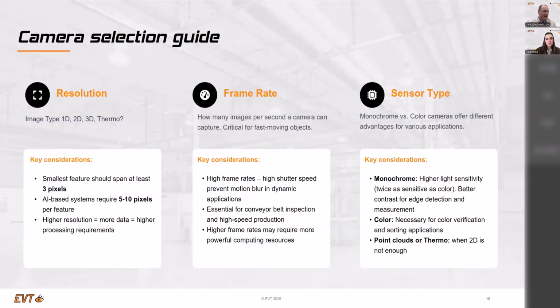Therefore, a higher image speed gives you simply some more calculation time in your main memory in your software than waiting to get the image. So this is one of the things why frame rate is really also interesting, because you save time. You have more time for the calculation. Let's say there are really not many applications in the world where you need 200 frames per second to operate on.